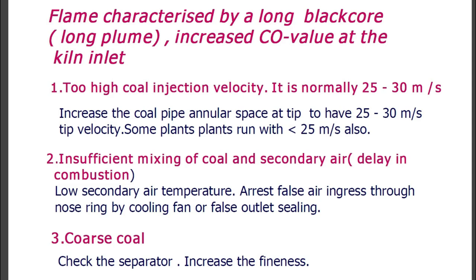Insufficient mixing of coal and secondary air. Low secondary air temperature. Arrest false air ingress through the nose ring by cooling fan or false air outlet sealing. Third point, coarse coal. Check the separator and increase the fineness.